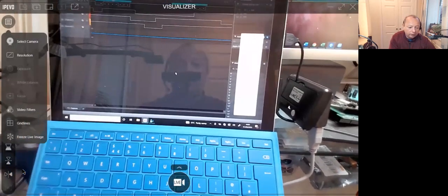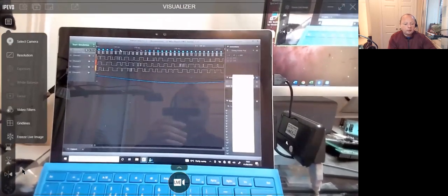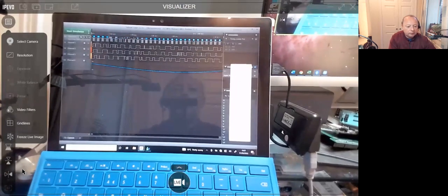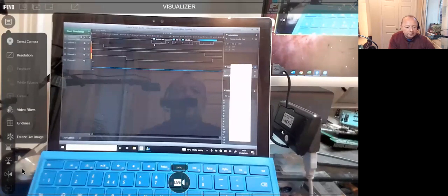Now, what I've got on here, which is really nice, just by way of example for us, is a load of data which I've captured earlier, just coming in over the UART. And then it'll decode for you and tell you, if I just zoom in, and you might just take my word for this, what it says. It'll actually decode the data that you've got coming in, and tell you exactly what it is that you've sent. So if you're sending, say, some AT commands, which is what we've got here,